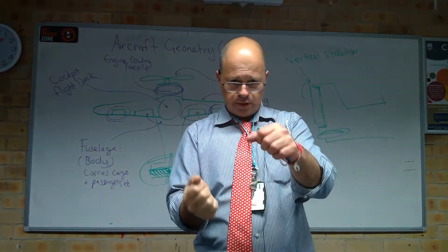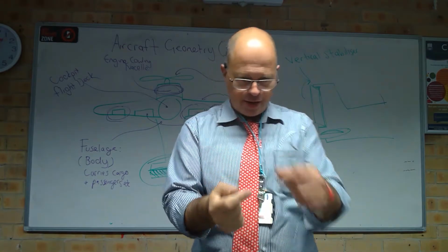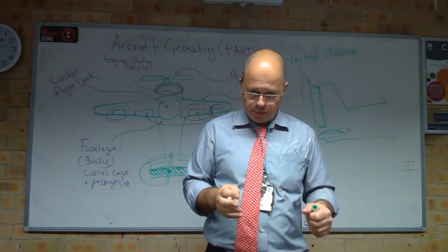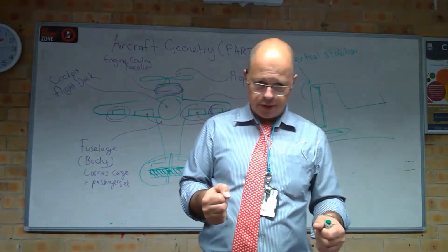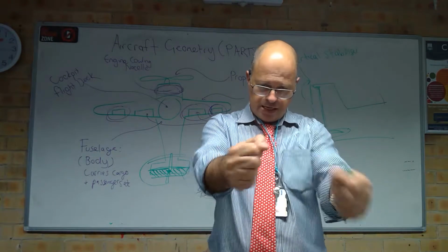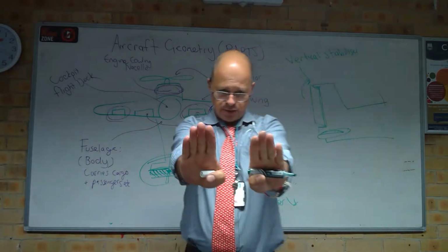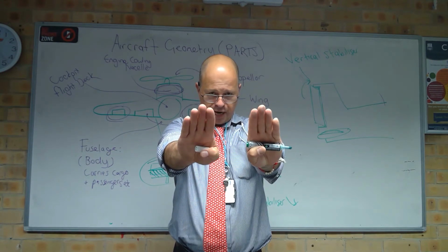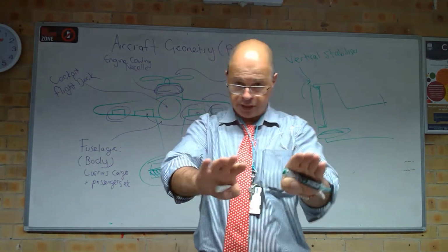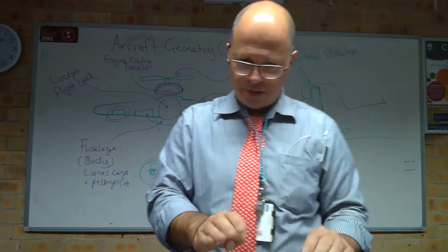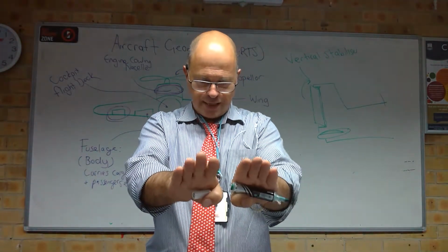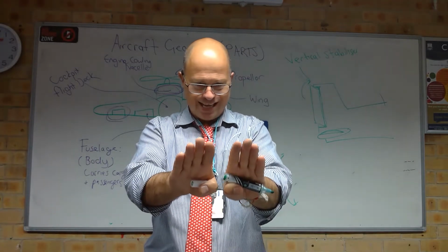And now you're going, okay, but that's a roll, and that's a roll. How do you control that? Well, believe it or not, it's not bad enough that you have to go up and down and right and left. Pilots also have 2 pedals. On the tops of the pedals, normally there'll be a brake that you can touch. You can actually differentially brake. You can brake the right wheel or the left wheel to help you turn when you're going slowly. You're not going to do it when you're landing. You'll push both brakes when you're landing.